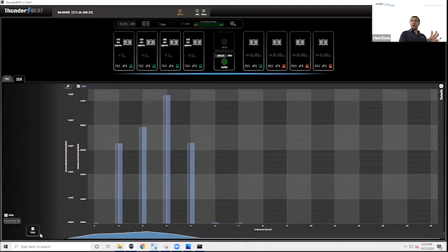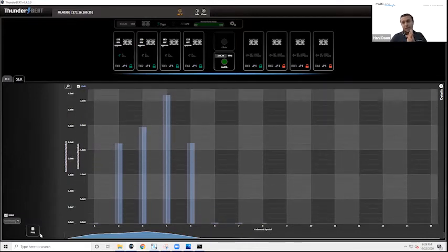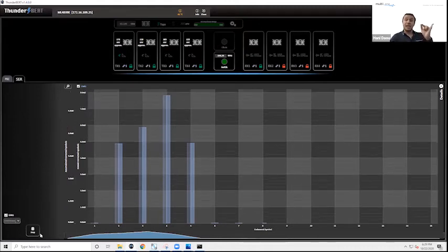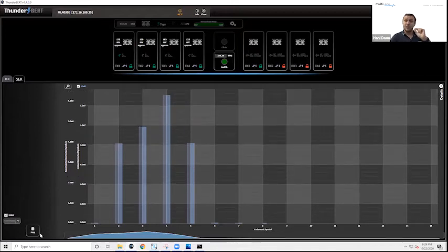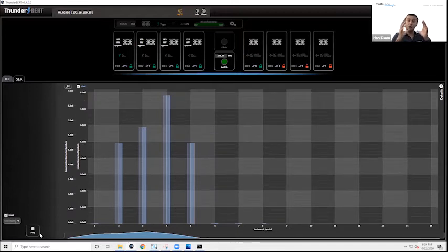So a quick note about SER and symbol errors in general. When a traffic stream is encoded with FEC, every 10 bits, this is an oversimplification, but that's okay, every 10 bits are transformed into a symbol. And then for KP4 FEC, which is the kind of FEC that we're using today, every 544 symbols, which is 5,440 bits, becomes a code word, a FEC block.